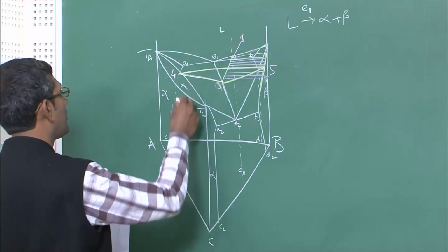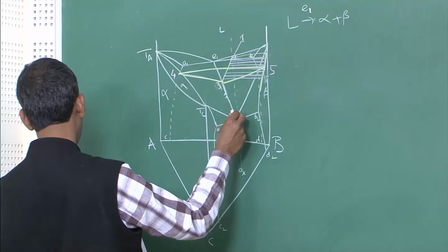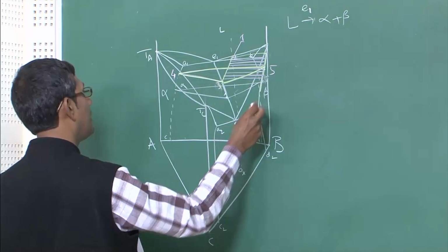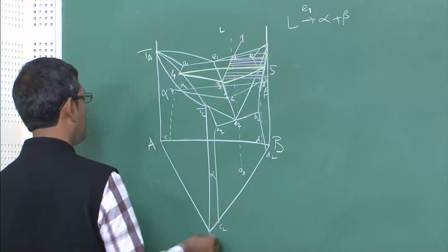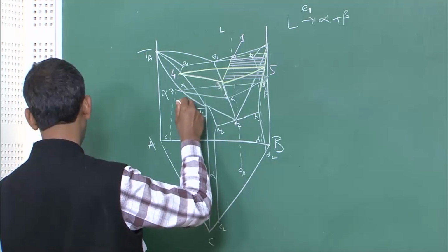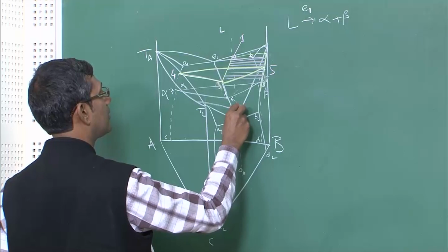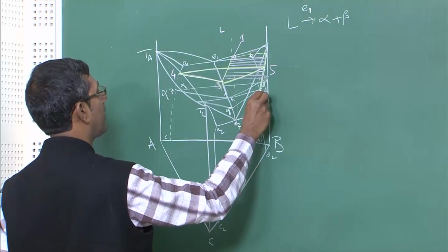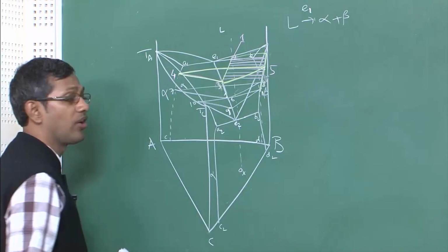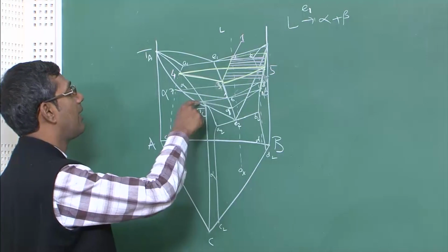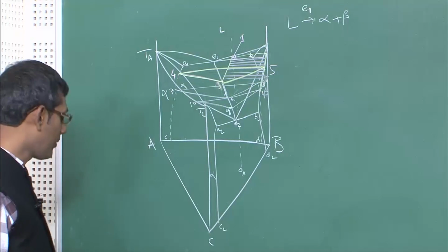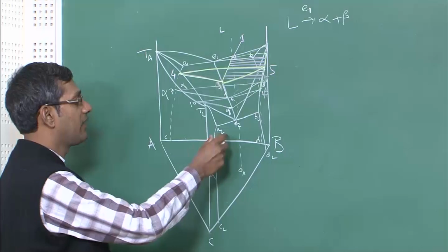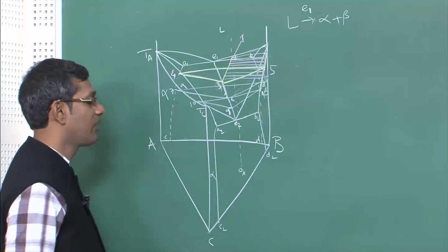Okay. And this is what will happen, this will keep on happening, and one can draw other triangles also at the bottom, like suppose I can draw a triangle between 6, 7, 8, let me just draw this way, this is another triangle, and similarly I can also draw another triangle below. You can clearly see this will be sitting here like this. You might be wondering how I am drawing these triangles. These triangles are drawn basically connecting points on the solid surface or the liquid surface here, and these two are the solid compositions alpha and beta. So, that is how the solidification will continue, and it will get over whenever it hits this alpha beta plateau here, which I have shown you last class.